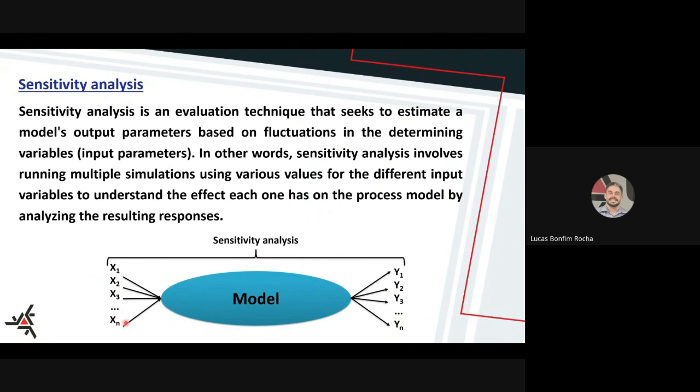Okay, for example, we are going to test different reactors with different volumes. I have the standard volume of 3 cubic meters, for example, and I want to assess the conversion of the reactor considering cases when it has 1 cubic meter, 2, 3, 4, 5. I don't need to perform many simulations.